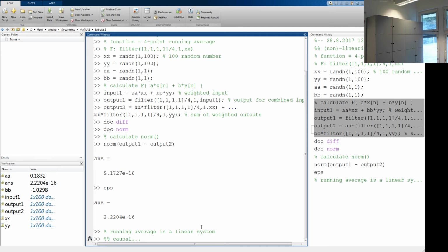So we take any random signal which starts at a certain point, run it through a system, and check if this one has any non-zero elements before this one starts. So it means that we basically need to start the signal, for example, like this. So we can actually use here the step function. And then we basically check this part here. That should be 0.